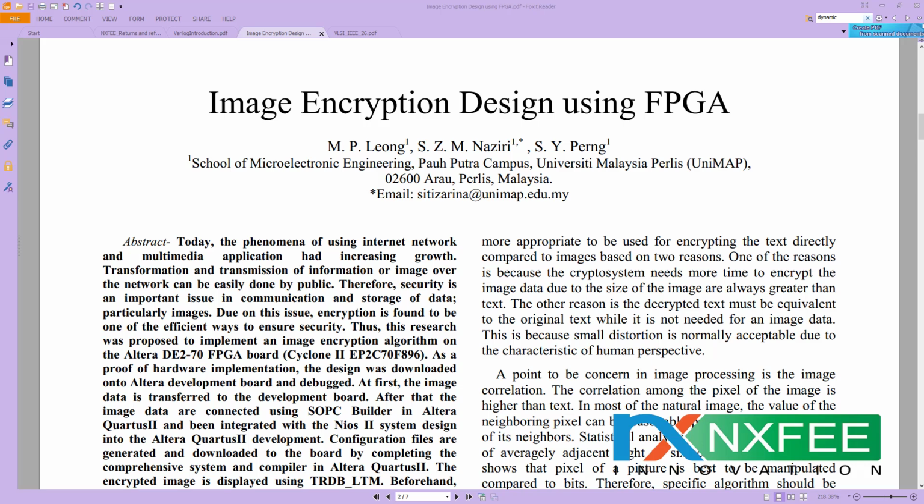The proposed system is developed using Verilog HDL and synthesized on a Xilinx Spartan-6 FPGA with a real-time TFT display interface for encrypted and decrypted image visualization. Traditional LFSR-based PRNGs are widely used due to their simplicity and speed. However, they suffer from predictable periodicity and lower security strength. In contrast, chaos-based PRNGs provide higher randomness and security, making them ideal for cryptographic applications.